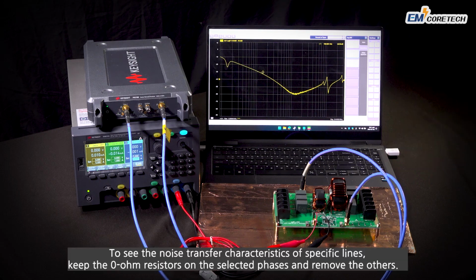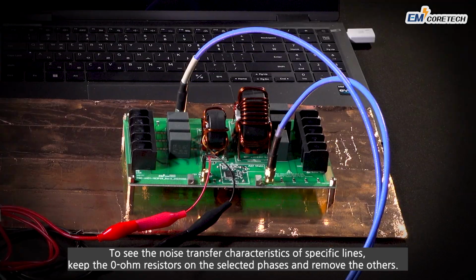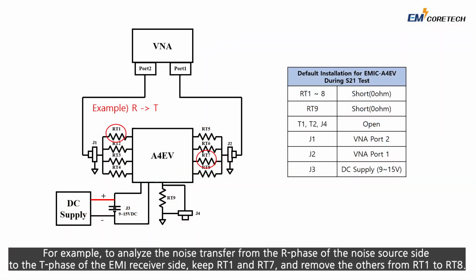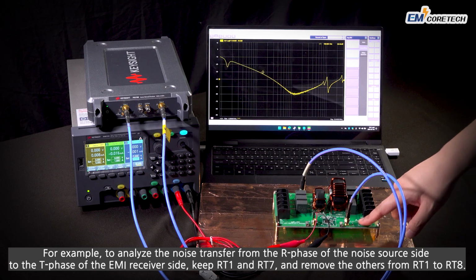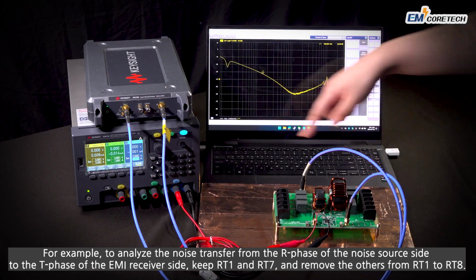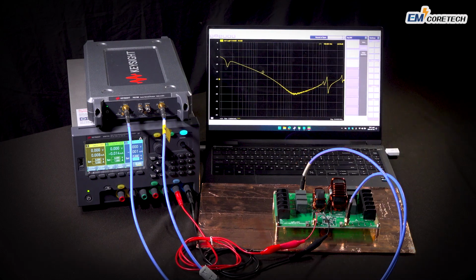To see the noise transfer characteristics of specific lines, keep the 0 ohm resistors on the selected phases, and remove the others. For example, to analyze the noise transfer from the R phase of the noise source side to the T phase of the EMI receiver side, keep RD1 and RD7, and remove the others from RD1 to RD8.